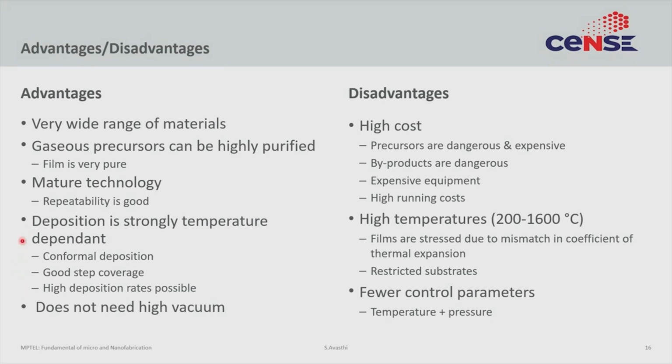In CVD, the deposition is strongly dependent on temperature. That is not very surprising because chemical reactions are often strongly dependent on temperature, which is given by the Arrhenius relation, which I think we discussed in a different context a few lectures back.